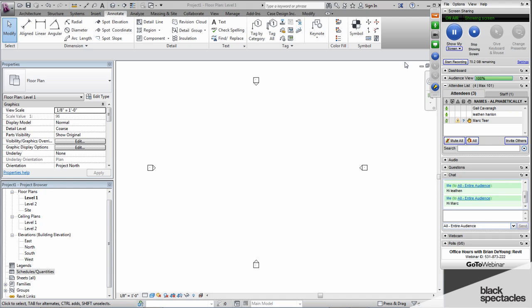And then when you change any one of those groups, they all update on every single floor. So rather than creating a bathroom and then having to make a change 5 times on all 5 floors, you just make the change once and it updates all 5 floors. And when you click on a group, the entire group highlights. So that might have been what you were seeing in some of the models.